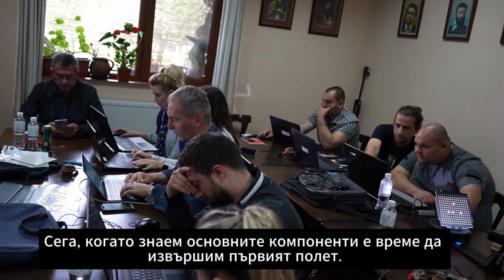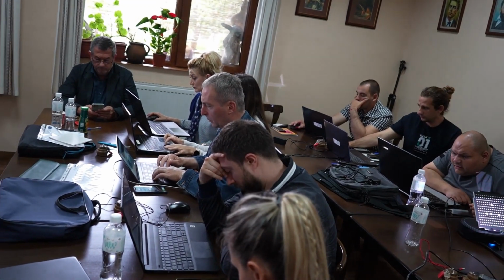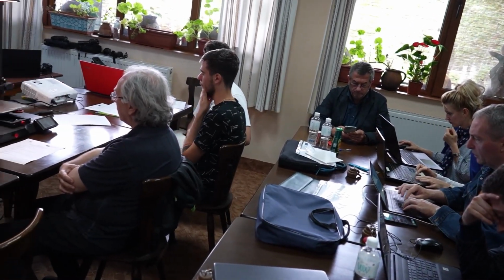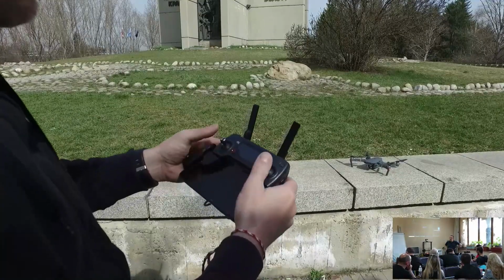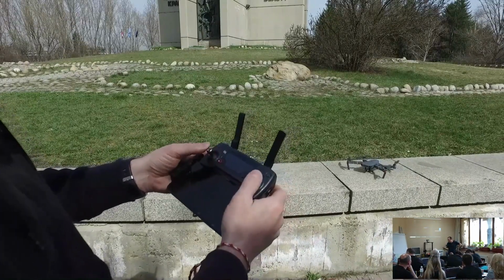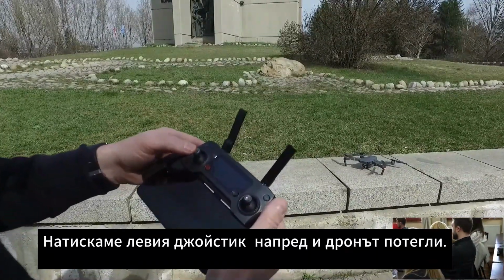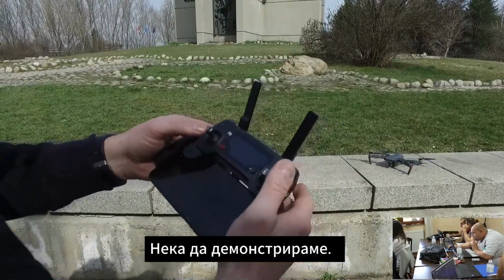Now that we know the basic components, it's time to make the first flight. To start the engines, we push the two joysticks diagonally inwards at the same time. We do it. And the drone's motors are already running. Pushing the left joystick forward, the drone will take off. Let's demonstrate.